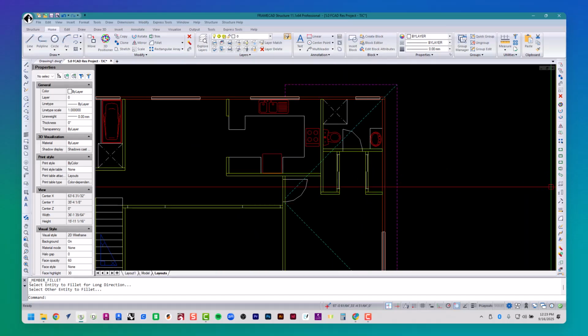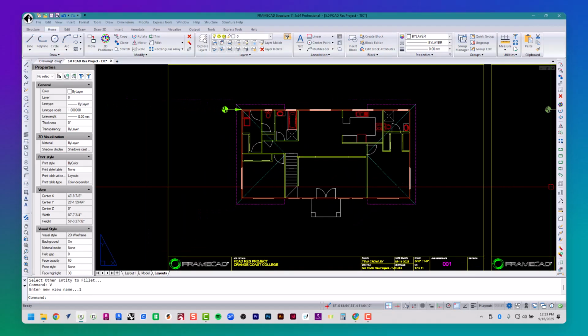Now it's time for us to add openings to our exterior and interior walls based on our architectural drawings. Typically the dimensions that define these openings will need to be the rough widths and rough heights versus using finished opening sizes. So we're going to make sure to quick navigate to border number 1, V, enter, 1, enter. Make sure that your first floor block is visible by turning on that temporary layer, LT1.